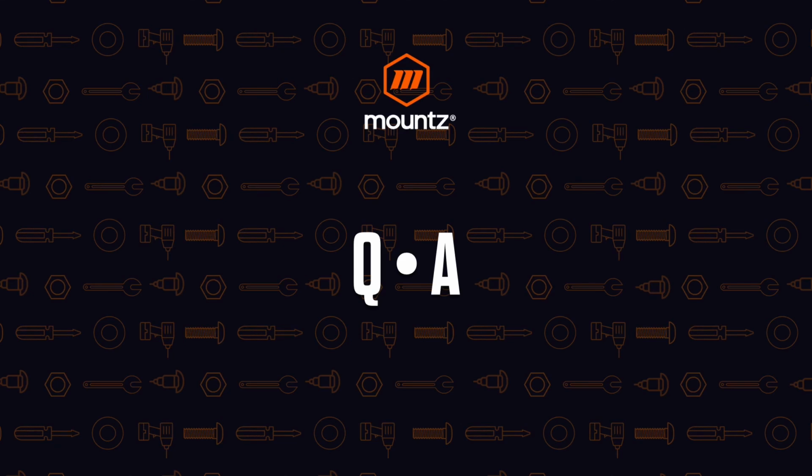All right, thanks, Dave. Last question looks like is the torque verification process something that you recommend like monthly or weekly on a tool, or even a shorter interval? Yeah, again, it will depend on how joint critical that particular tool is being used for. So we have customers that will validate their tools once a month, or once a week, or once a shift. It could be the operator comes in the morning, they test their tool, make sure that things are working correctly. Then they go ahead and put those tools in service.